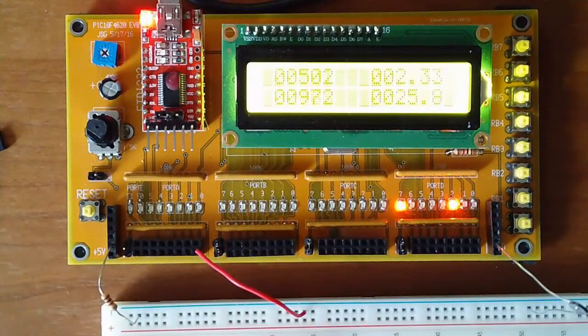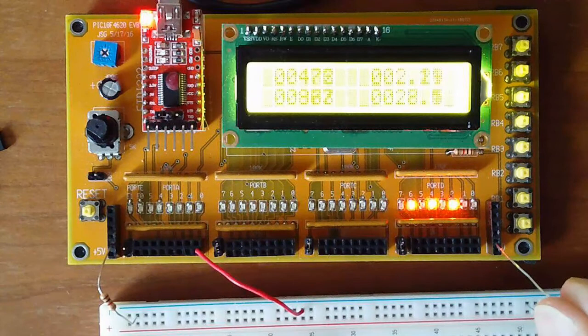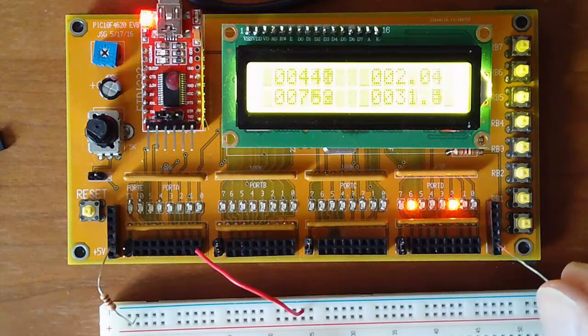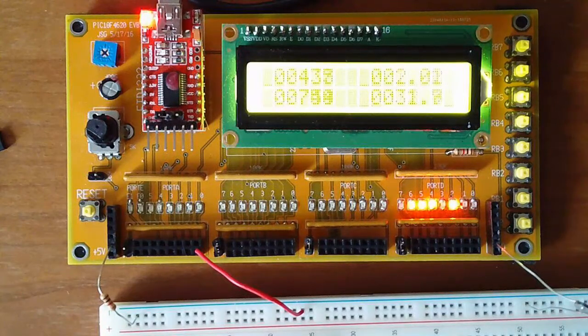And I've got the raw A2D reading, the voltage, the resistance, and the temperature in Celsius. So this says currently it's 980 ohms, which corresponds to 25.6 Celsius. If I warm it up, I'm sticking my hand on the thermistor. It's warming up to 30 Celsius, 31 Celsius, 32. I now have a temperature sensor.